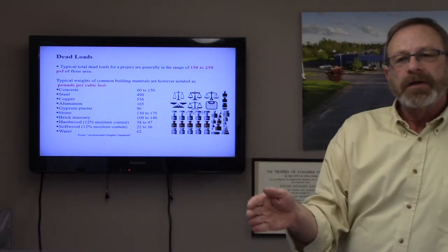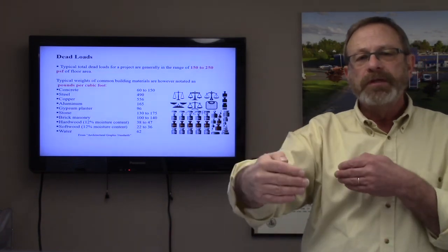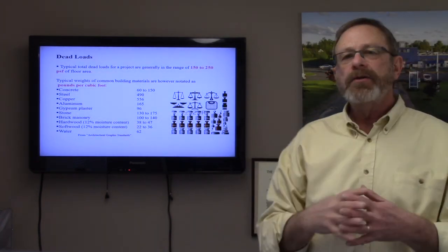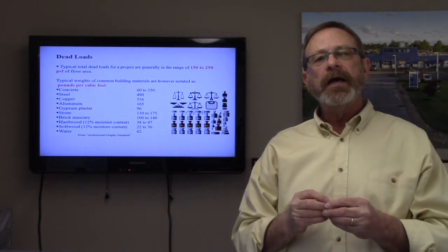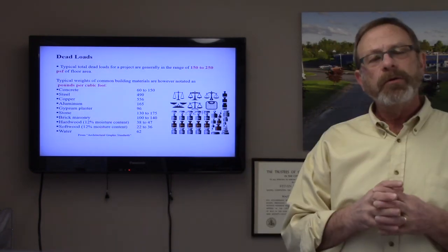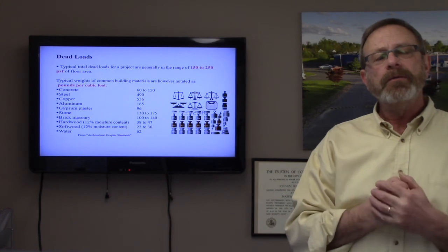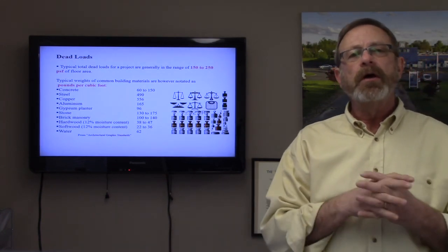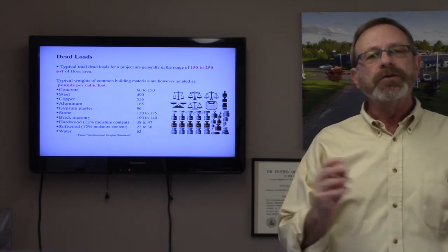That's a box 1 foot wide, 1 foot tall, and 1 foot deep. So we can calculate, knowing the quantities that we expect of the materials in our design, multiplied by the pounds per cubic foot, the loads that are going to be expected to bear on the ground or the soil below that building in order to make sure that those soils are sufficient to resist that load.